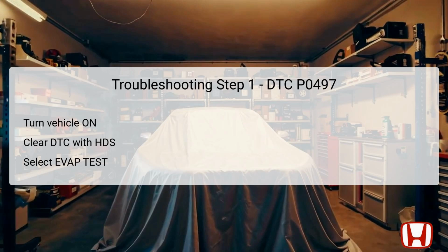Check for loose connections or poor terminal contacts with key components, like the FTP sensor, the EVAP canister purge valve, and the Engine Control Module, PCM. In this troubleshooting step, you need to turn the vehicle to the off lock mode, allowing you to safely inspect the EVAP system components. Focus on the EVAP canister purge line, which connects the intake manifold to the EVAP canister. This component is crucial for ensuring that vapors are efficiently transported through the system.